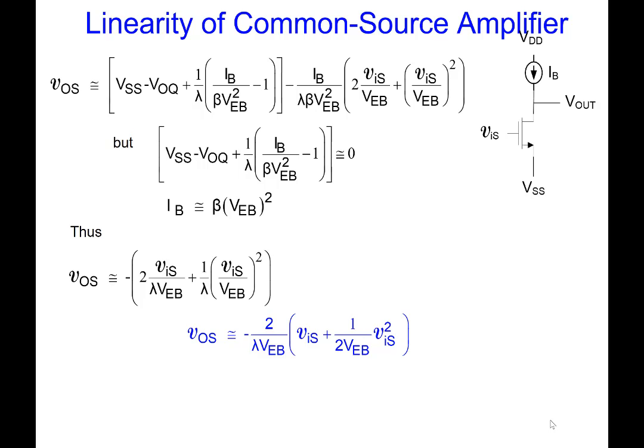So here's the small signal output. Now in terms of these practical parameters really look nice, don't they? Because we had these ugly expressions in terms of the natural parameters. We get back these practical parameters, and we have a pretty simple expression. Ms. Poon, what can we do to improve the distortion? What does the designer have control of? The excess bias.